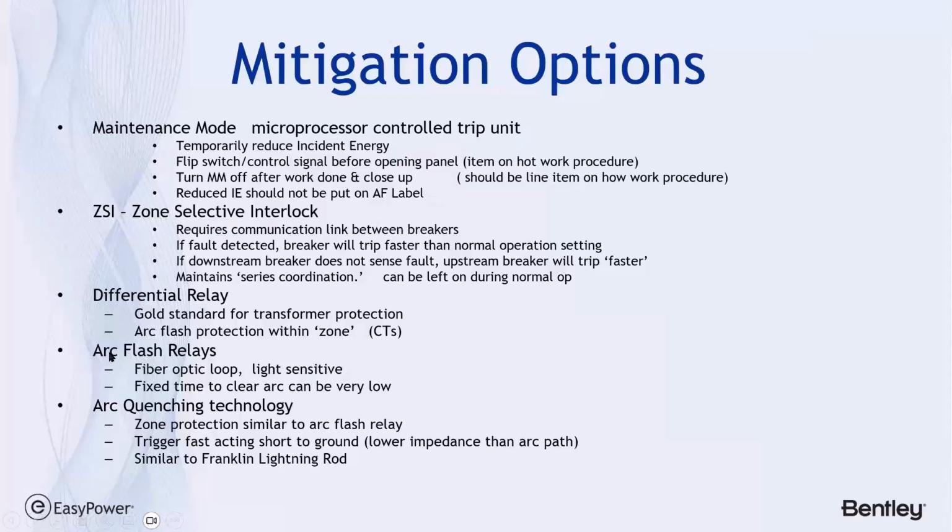Now, arc quenching is a more recent technology these days, and we can't simulate its operation. There are multiple ways of getting the quenching, but basically it does a hard fault, or a crowbar, on the bus that's protecting the system, and it has a very fast trigger to redirect that current to ground and blow the main fuses.